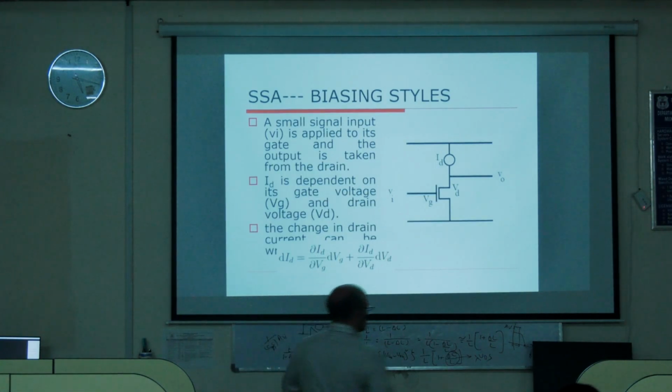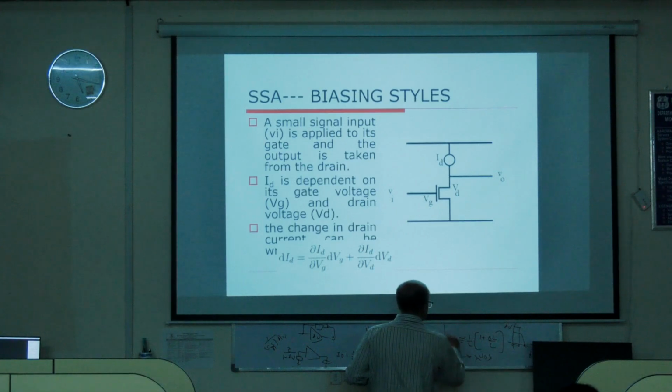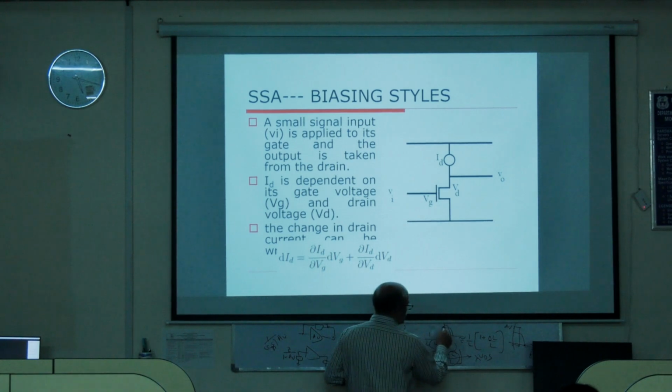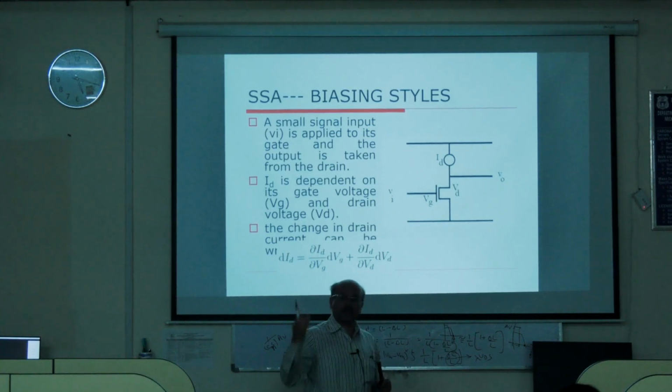Now I want to see that for the same unity gain bandwidth, earlier it is like this, right? So this is here, I want to go here. If I want to increase the gain, but I don't want to change this unity gain frequency, for the same unity gain frequency, I want to get a larger gain.